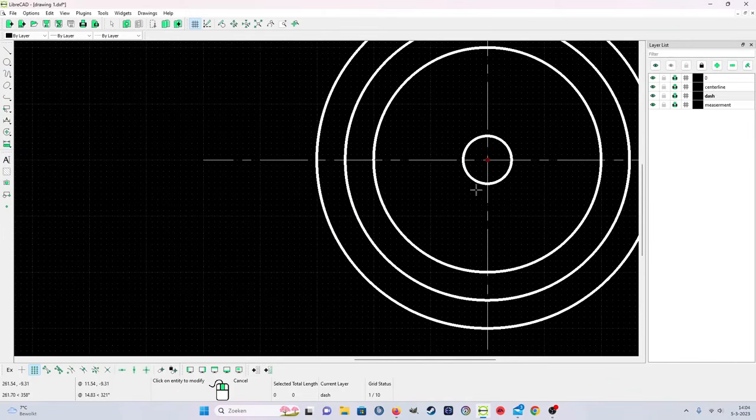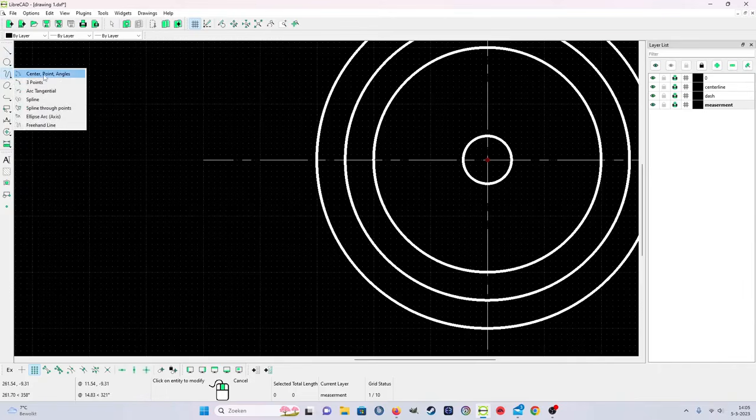And now normally you put a small broken circle around the thread hole. We're going to use the measurement thickness, and then we're going to here, not this one, not this one, but the third one. And then you set center to point angles. The center point angles.